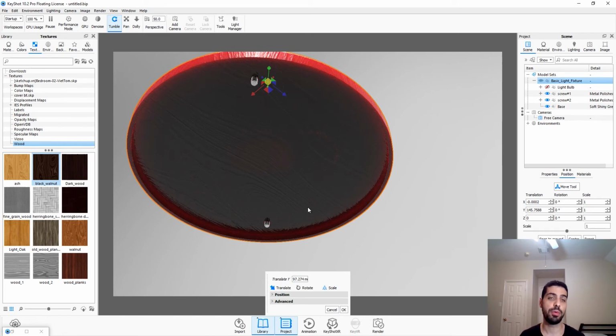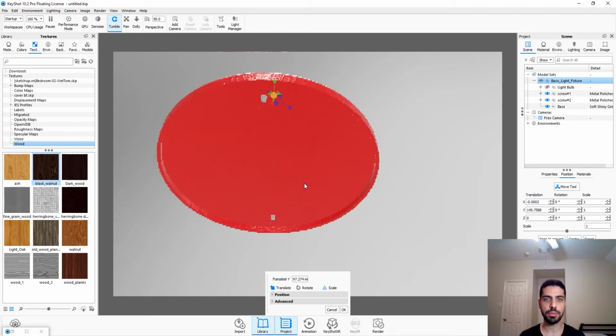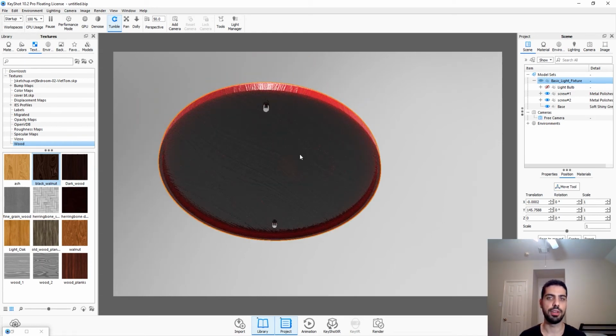And I ran into a problem where I can't really detach or take off the support from this, because the support actually follows the pattern of the model on your STL file. So what you can do, you can either separate the surfaces if you want to, and then don't put the pattern at the bottom of the model.